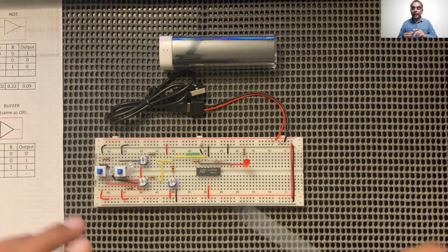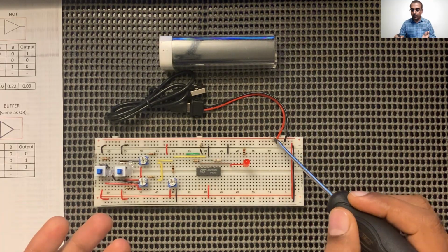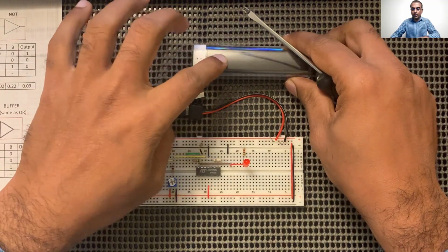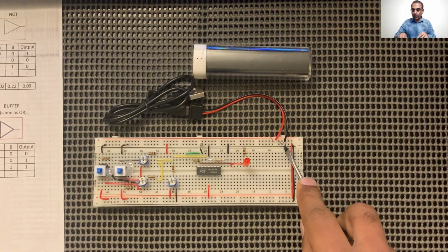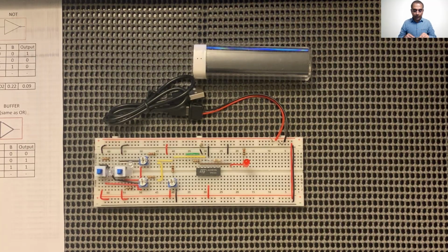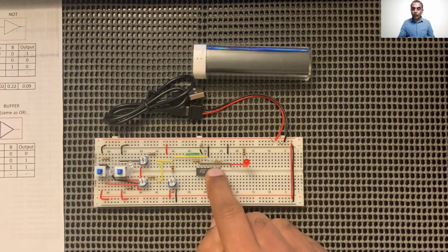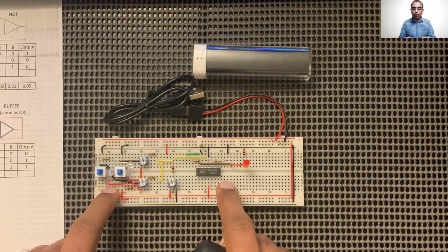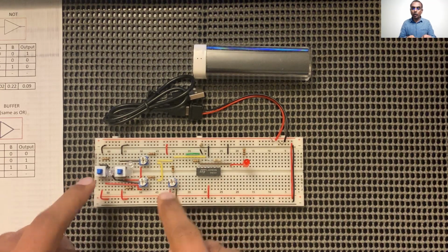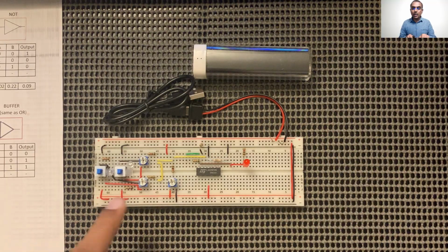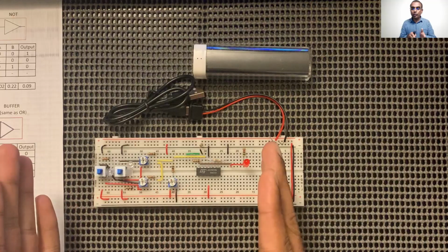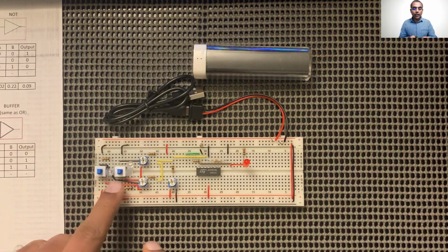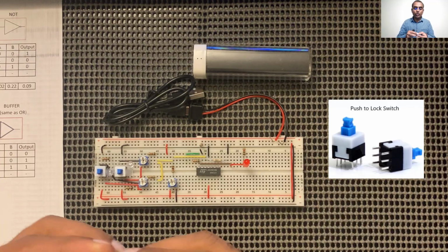This is the breadboard, and it has two power rails. The plus 5 volts is coming from the battery, that is this USB connection, and the black wire is connected to the ground. It has jumper wires, a bunch of resistors, switches, LEDs, a potentiometer, and an operational amplifier. The jumper wires help us connect the breadboard from one node to another, or from one component's terminals to another. The resistors are used to limit the current that is flowing through these electrical components. There are two switches here. I have a small switch here to represent.